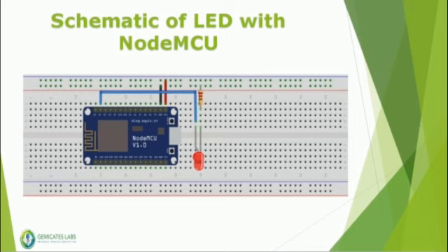This is how the schematic of LED with NodeMCU looks like. For interfacing LED with NodeMCU, we are not using Proteus software because NodeMCU consists of an inbuilt Wi-Fi module, but Proteus does not have any Wi-Fi module library and hence it cannot be added. So we are going to interface it using Fritzing software, but using this software we cannot check the output. Using this software we can design the simulation part.